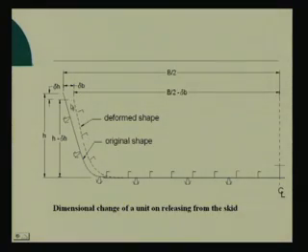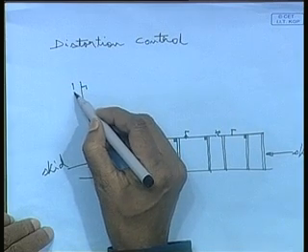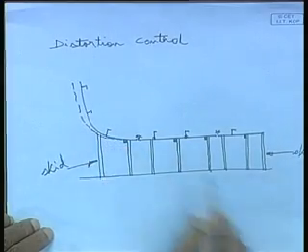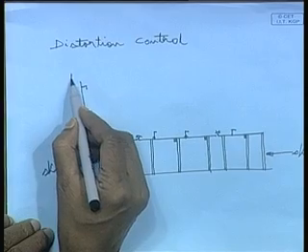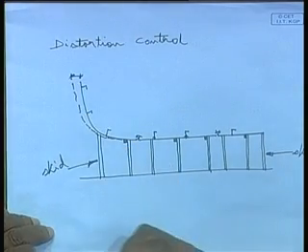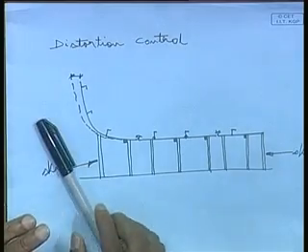That means here you provide suitable shrinkage allowance, whatever shrinkage is taking place, such that this shortfall in height is taken care of, as well as this shrinking. You will have to provide the allowance such that after shrinkage it will shrink back to the design dimension. In other words, one has to properly estimate the shrinkage allowance.